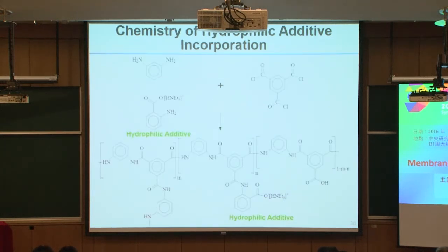So what we have again is meta-phenylene diamine, and this is in the aqueous phase. In addition, we also put in this hydrophilic additive, in the water phase, and this is in the hydrocarbon phase. Those two react through the interfacial polymerization, and then we make the interfacially polymerized polyamide membrane.